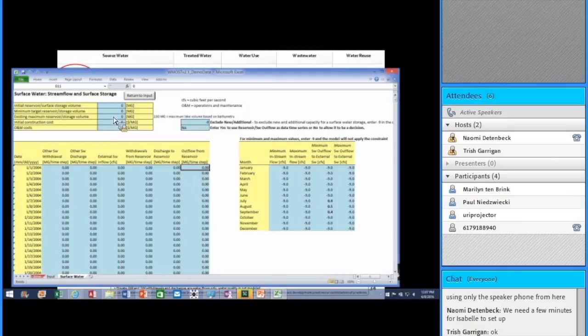So, for example, if you have a drinking water reservoir, you might have another town that withdraws from that reservoir to meet their demand, and you want that to be reflected, because what you're going to be modeling is what this utility's effect on the reservoir is, but there's also separate withdrawals that would not be accounted for in the system unless you add them separately. There's an outflow when it gets that.